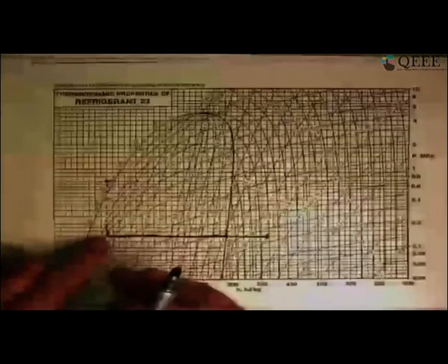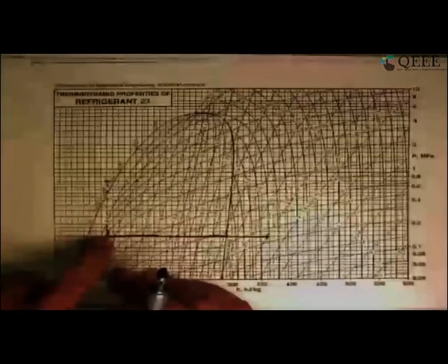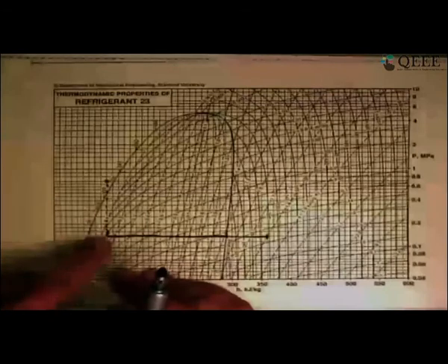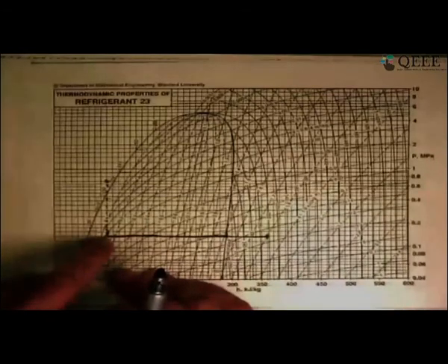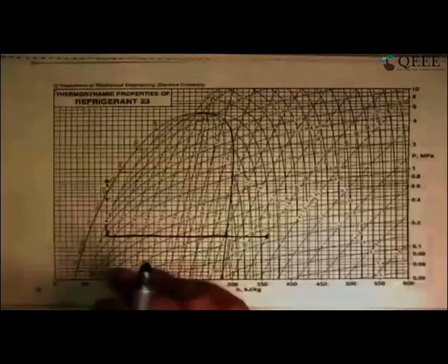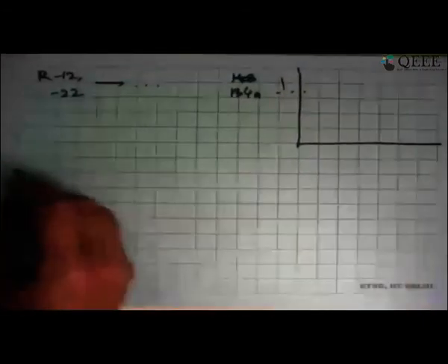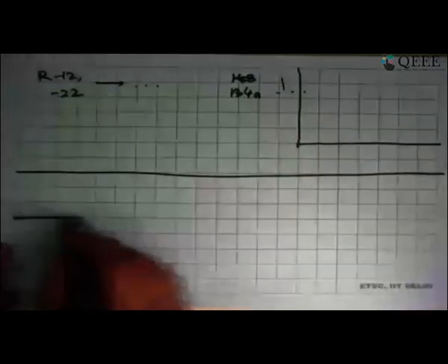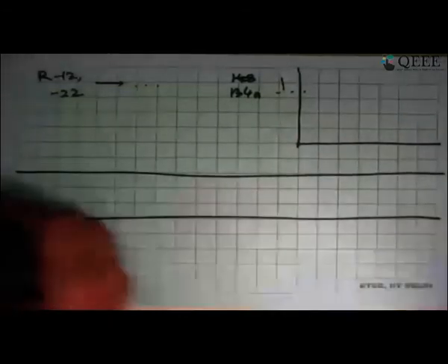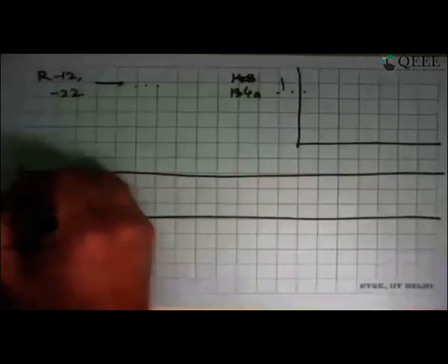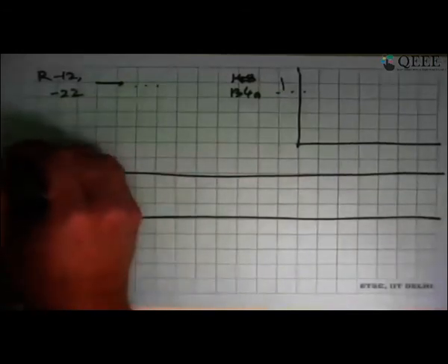The point of putting this out is that the entry state into the evaporator is not a saturated liquid, but a wet state, about 10-15% quality. That's the difference. But what I'm going to explain now is, let's not worry too much about whether it was 10-15% or not. We will see a tube into which at this point we introduce saturated liquid.